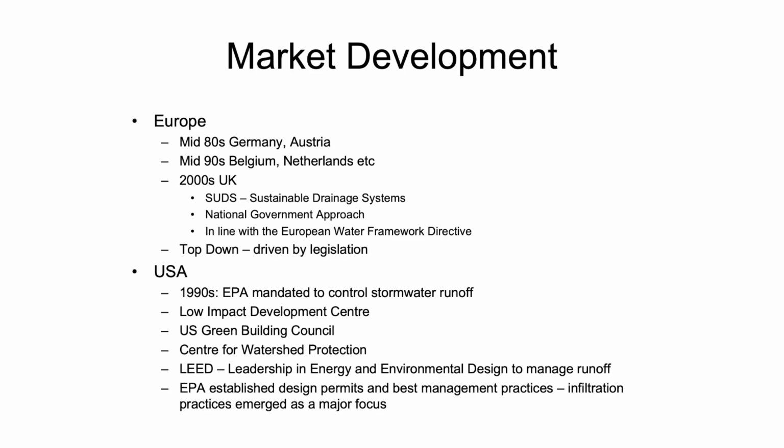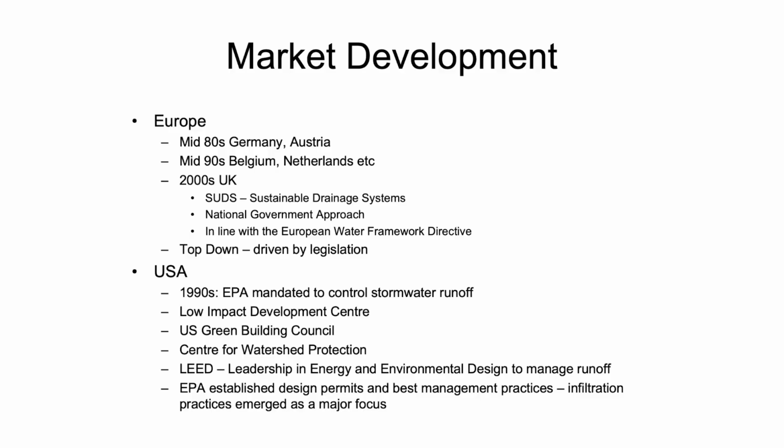So Germany and Austria, worth looking at. Belgium, on the other hand, went down a completely different path. In Belgium, they add cement into their base course material, so they can use permeable paving on moderately high-speed roads and very, very heavy applications. But you don't see cement being added very often in Australia or in many other countries in the world. So be careful when you look at a Belgian system. It's very differently designed, but very much backed by their government. They've got a national design centre funded by the Belgian government purely for paving. Okay? So the Netherlands also put a lot in, not to the same extent as those other countries.